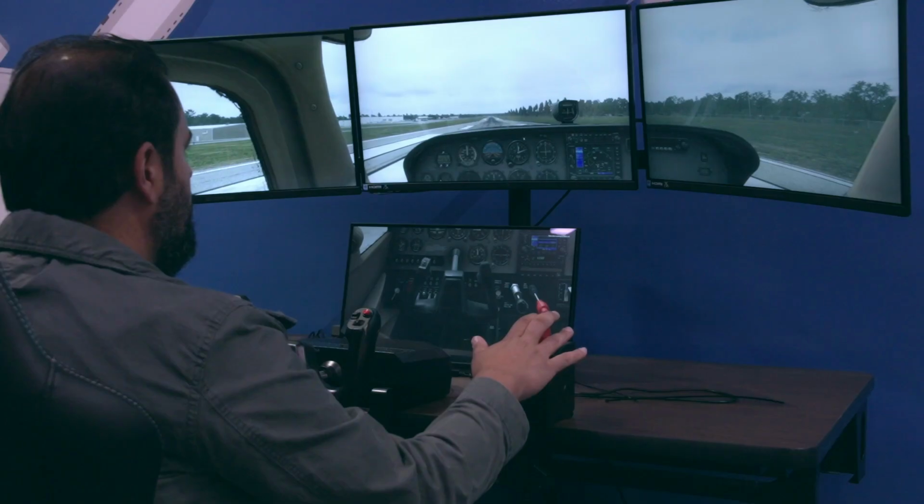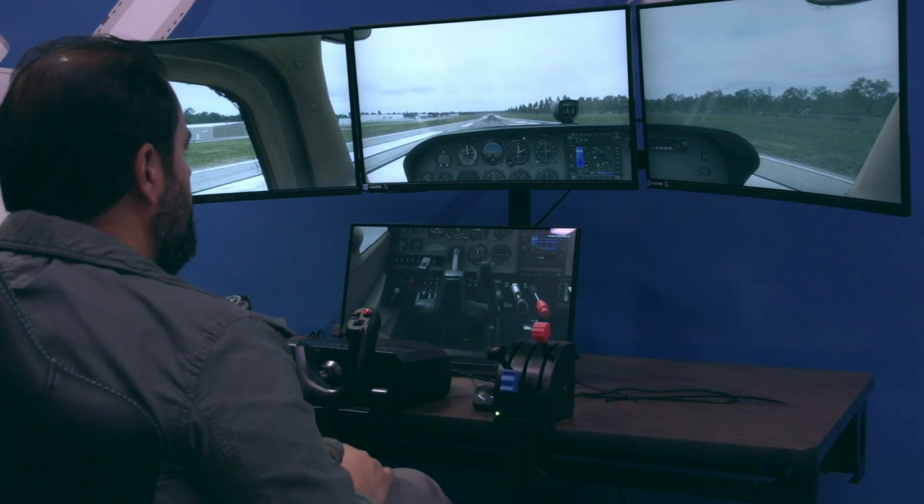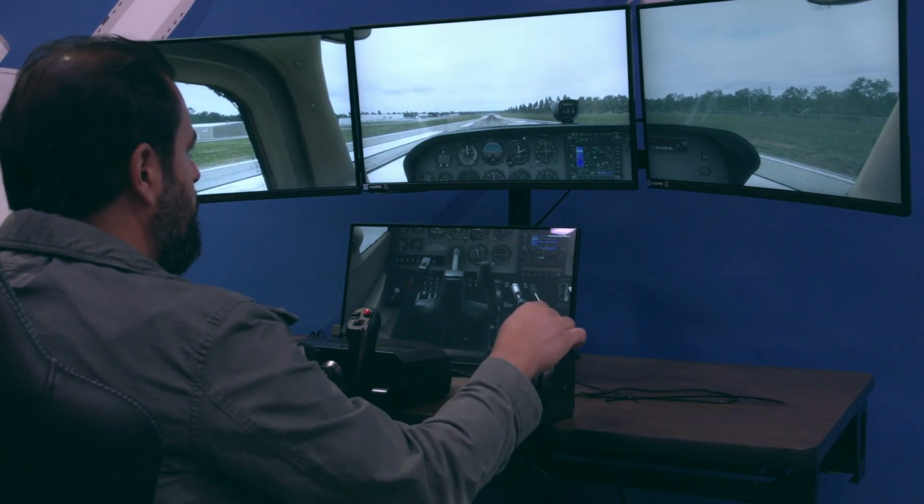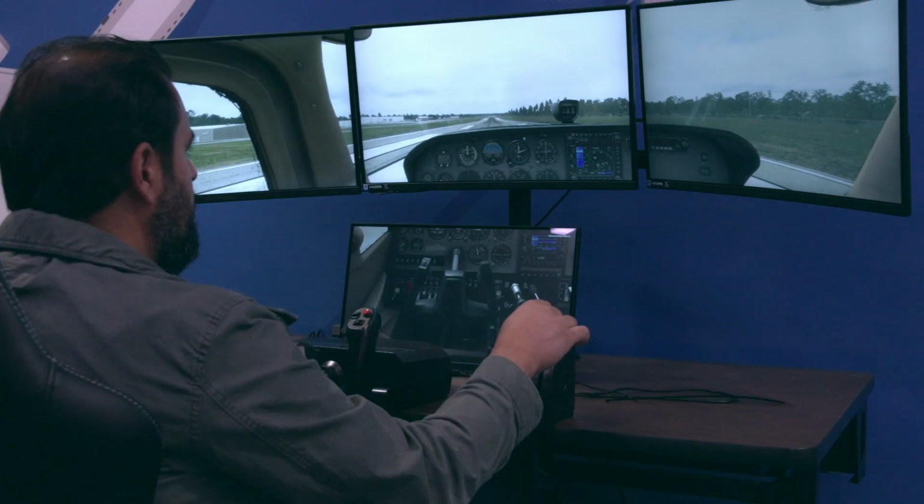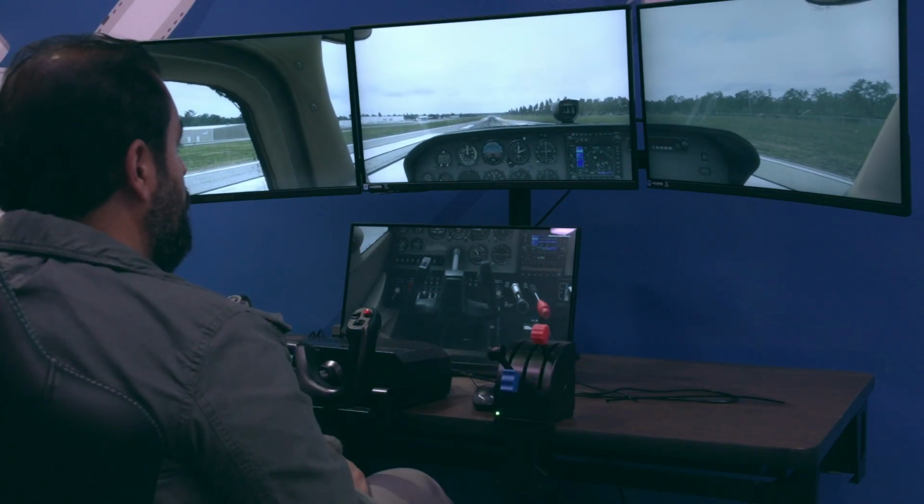When you release the brake, you want to keep in mind that the rudders for this specific device are usually uncalibrated, and this is a software bug based on what we hear from the company. So you need to play with the rudders a little bit to make sure that you remain on the tarmac. Okay, so you want to make sure you don't really provide the full power at the beginning, just a little bit so we can start moving.